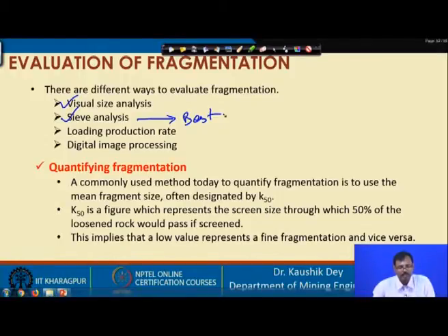All those criticalities are there, and it is almost practically impossible to carry out sieve analysis for a blasted muck profile. Blasted fragmented rock muck cannot be sieved. So, though it is the best, practically carrying out this exercise is almost impossible, and that is why we discard sieve analysis in most blasting cases.